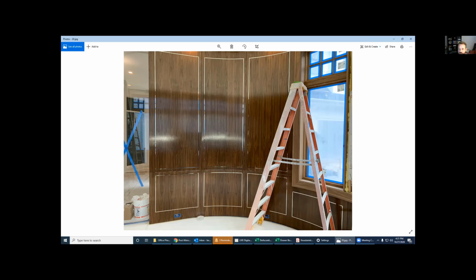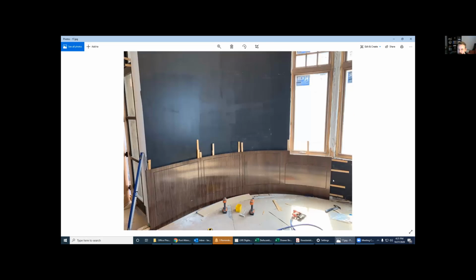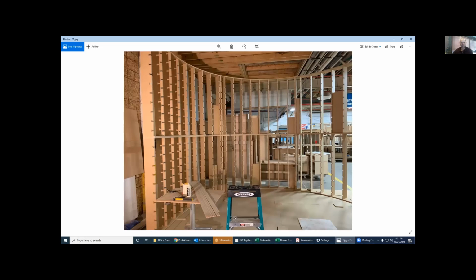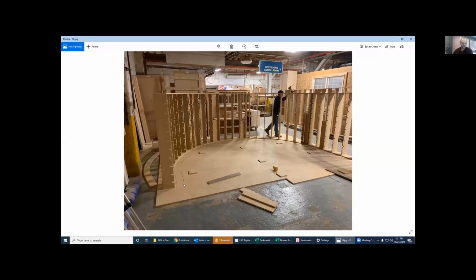So those faux walls you created that you showed in the earlier pictures, the framing, that's what you used to build. Yeah, all of this, and it's pretty slick. If you're not familiar with SMT, you really just draw a 2D view of this stud with the notches and the spacing that you want. And then in plan view, you draw the radius line that you want and tell it to extrude on that line. And it snapped all of these parts in on the spacing and nested each one of these cuts.